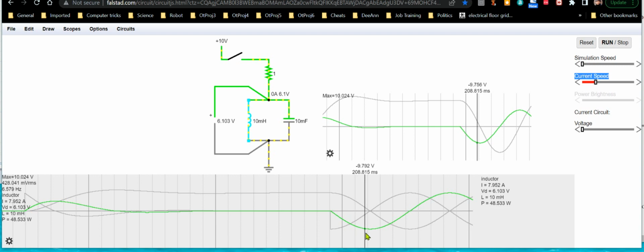And that's the thing that always used to confuse me: okay, capacitors, they've got a bigger voltage across them. Well, how's that? Isn't it gotta try to transfer it to the inductor? No, because the inductor is fighting. The capacitor is not losing energy at all. Its energy is increasing. And the reason is because this inductor keeps generating a slightly higher voltage across the capacitor. As long as the inductor has life in it, in other words, energy, it will generate a slightly higher voltage across it than the capacitor has in an effort to try to maintain its current.